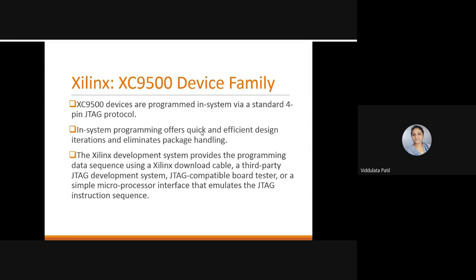In-system programming offers quick and efficient design iterations, and it eliminates package handling. So that is the advantage of in-system programming. As I said earlier, because we are programming the device while it is in its chip only, that means on its board only, handling is not required, and so that is the advantage.